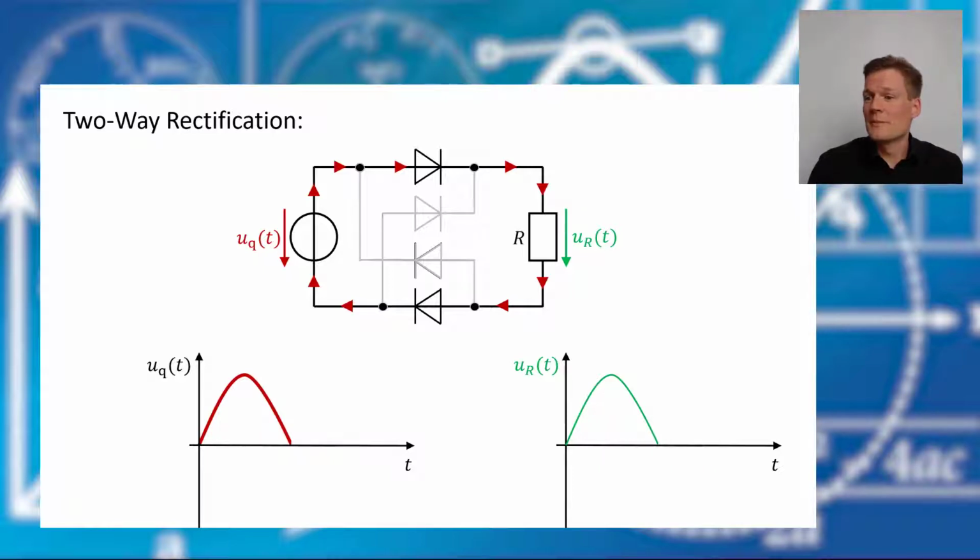But now the algebraic sign of the voltage source flips, and that means that the current would leave the source upside down. Okay, and the current would leave the source in this direction, and you see it can't travel through the diode it used the last time, but there is a new path and now the current can flow here.